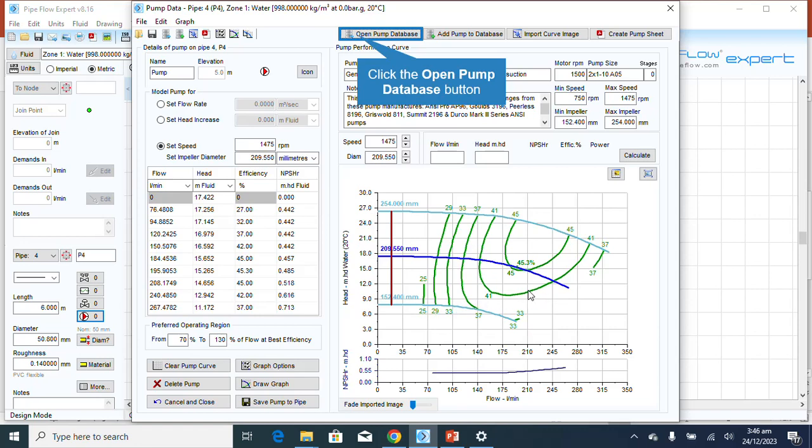Now if we use this particular one, you might not be able to ascertain whether what you're using is okay or not. But first you need to set a flow rate, then calculate the head. If you calculate the head, you don't come here, this is 280, you come here 250, you go select.